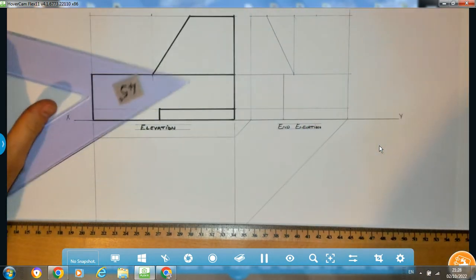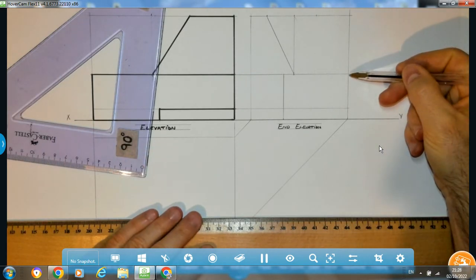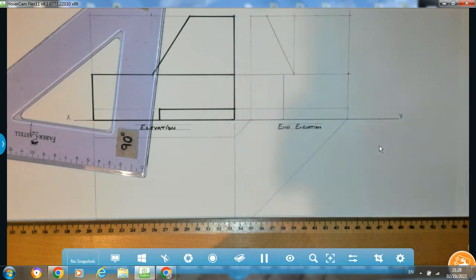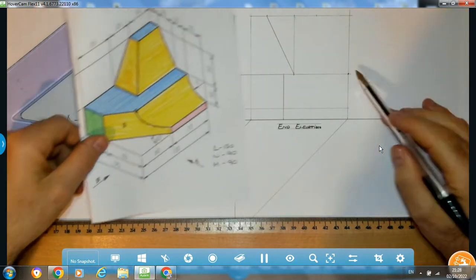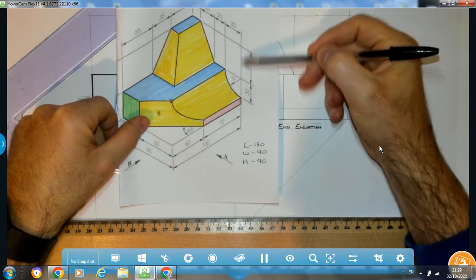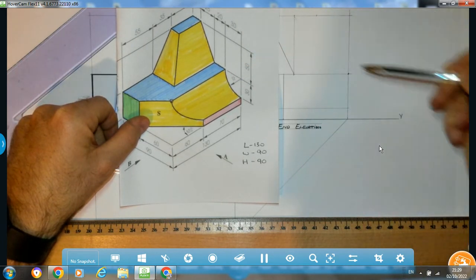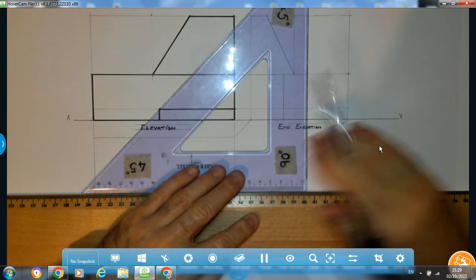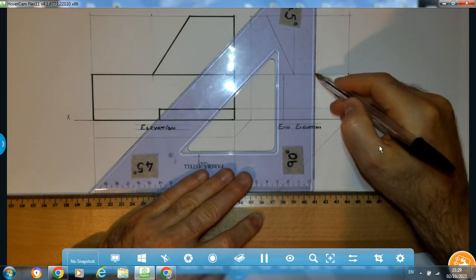And now the last little bit we have to put in then is our semicircle, okay, or our quadrant. So here is our radius. Center point of our radius is right there. Okay, you can see that point right there. It's directly up from here. It says R, but our radius is going to be 30 because that's the distance there. So I'm going to mark back 30, which is this distance here. So I'm actually just going to bring that down just to give me a little guide rather than having to measure it.